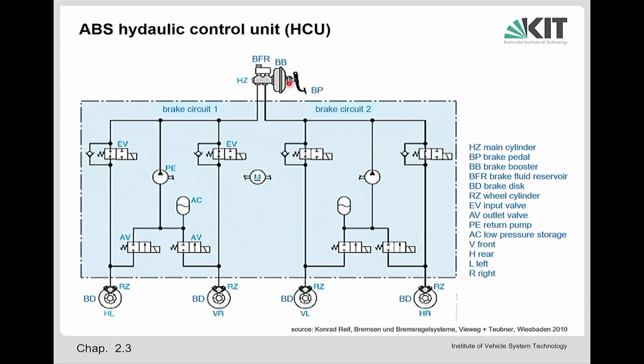And so if the brake pedal is pressed, the booster amplifies the brake pressure, so we will have a high pressure here in the main brake cylinder. And if more brake fluid is necessary, no problem. Here's enough in the reservoir. So then the fluid will be pressed along the line, and you can see there are two lines, one to the left, one to the right. So this is circuit 1, and this is circuit 2.